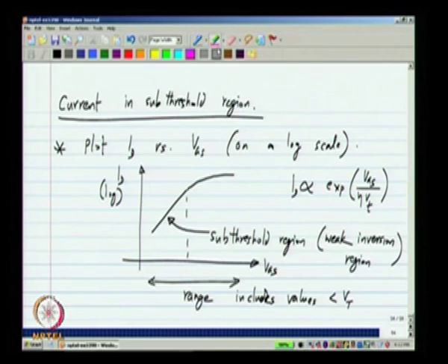Okay. So, the point of this exercise is first of all to identify the subthreshold region, and secondly, from this region you can get the slope eta. Okay. You can calculate what the slope should be and what the slope is of this straight line, and from that find the factor eta. Okay. We will discuss this a little more later, but you can see that if eta is close to 1, then it will be better because the exponential will be really steep. Okay. So, that is the point of this exercise. Again, do this for both NMOS and PMOS and familiarize yourself with the MOS transistor.